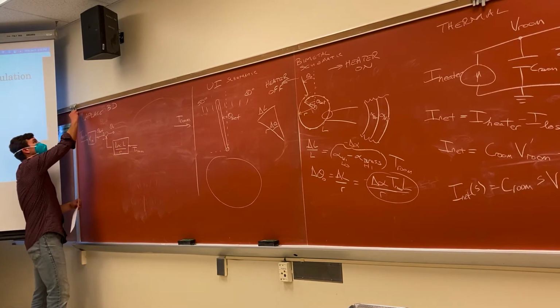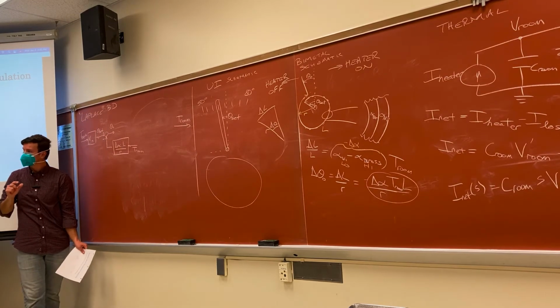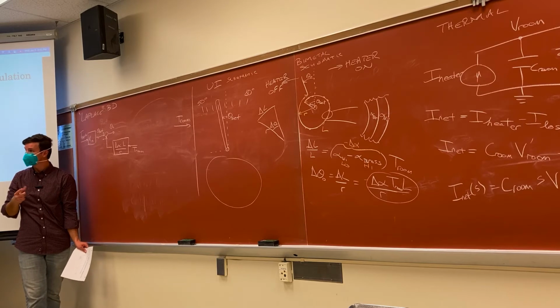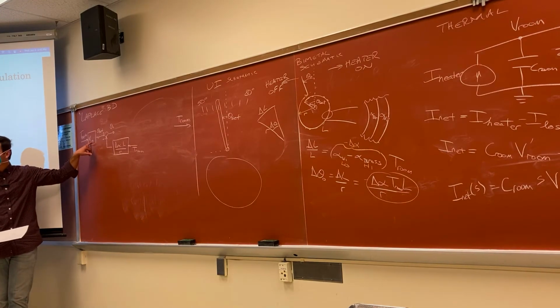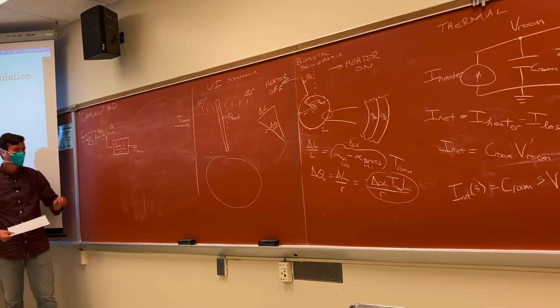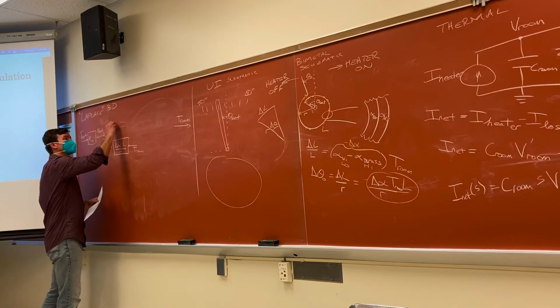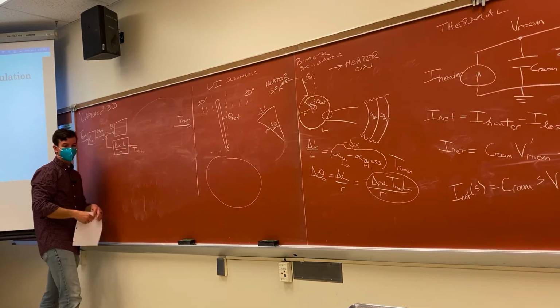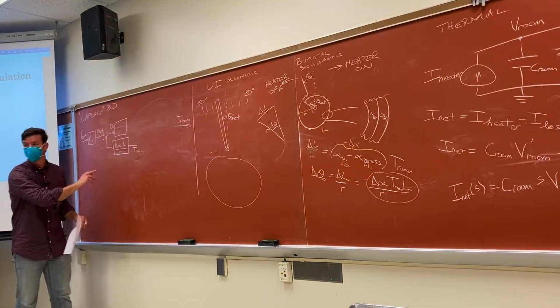Here is where I have to put quotation marks around Laplace, because we're coming up to a non-linear element, that is, a binary switch. Okay? What is the K U block? Whenever I come across a constant in this class, I'm probably going to call it K. So this is just some scaling factor. So I will give you a fair warning here. This is not strictly speaking a Laplace block.